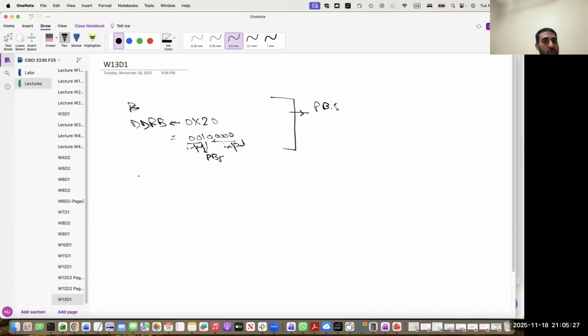But what we want is to not affect other pins. We want to keep them as they are. We don't know what their status is, right? So what we can do is write this instruction, set IO bit. Oh, I got your question now. I was trying to guess your question, but let me finish and I will come back to it. So when you say DDRB 5, all other bits will retain their older value. This bit will be set equal to 1 and it will be output.